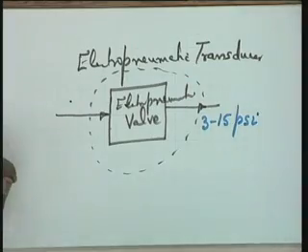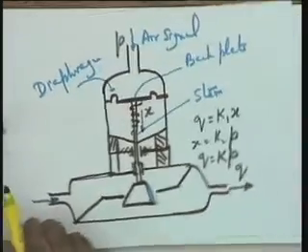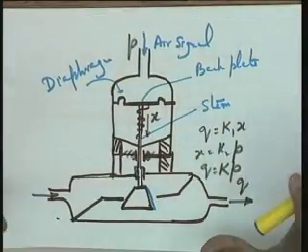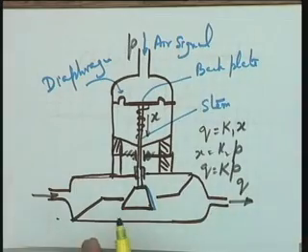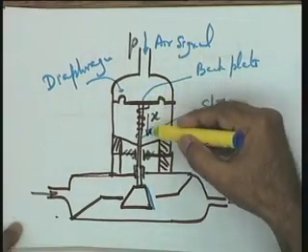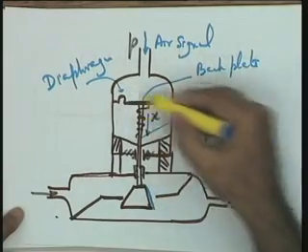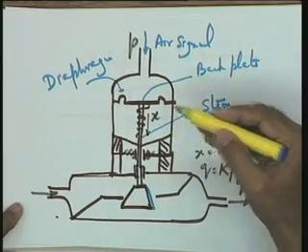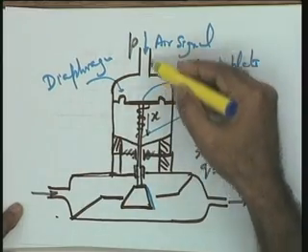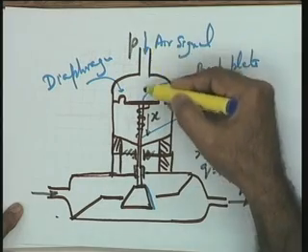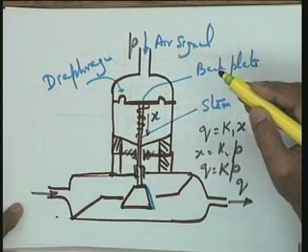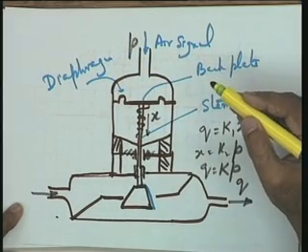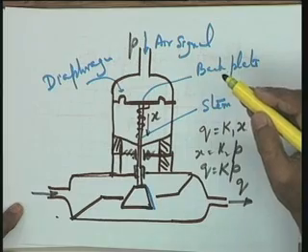It means in this particular case, the control valve is also suitably designed. After all, this is a total unit. So, the control valve, the backplate, the diaphragm and other components of this device are to be designed assuming that the input is 3 to 15 psi, the signal coming from an electro-pneumatic transducer.